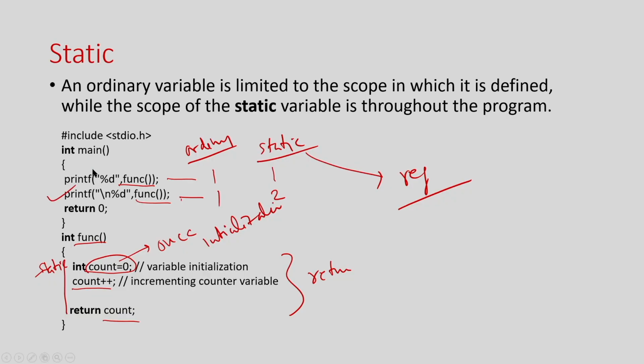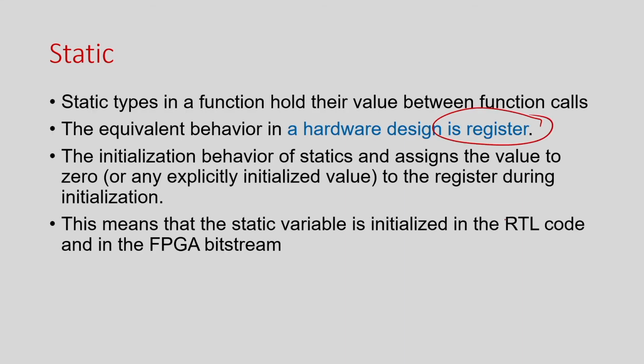And because in hardware all modules are actually running in parallel and they will remain live throughout the execution of the program, whenever you call the second time, it will actually return you the modified value. So, the basic point that I try to mention here is that for a static variable we have to realize this using hardware, and it must be initialized, right.